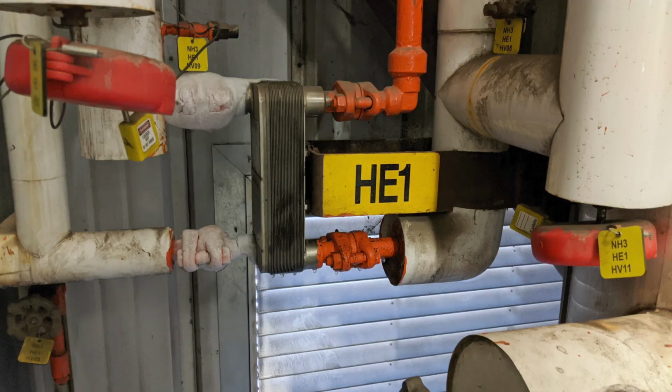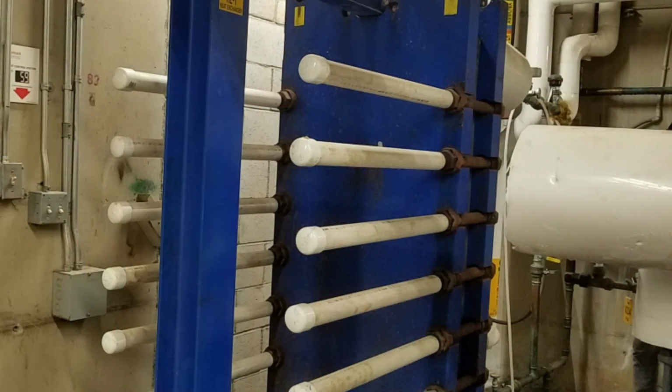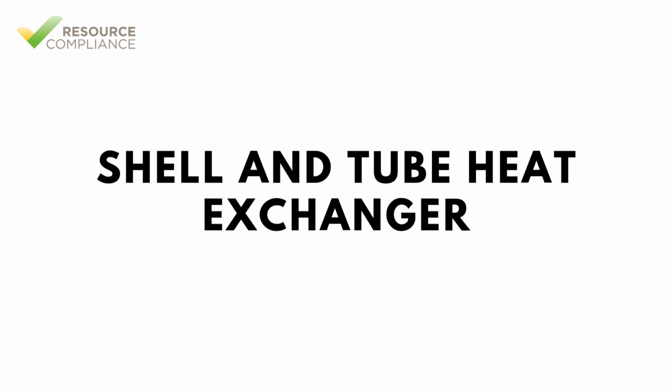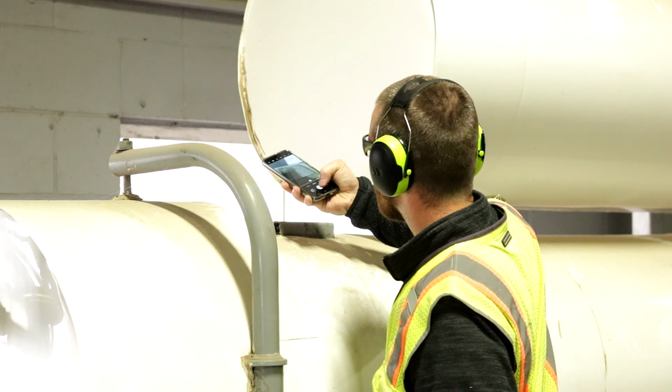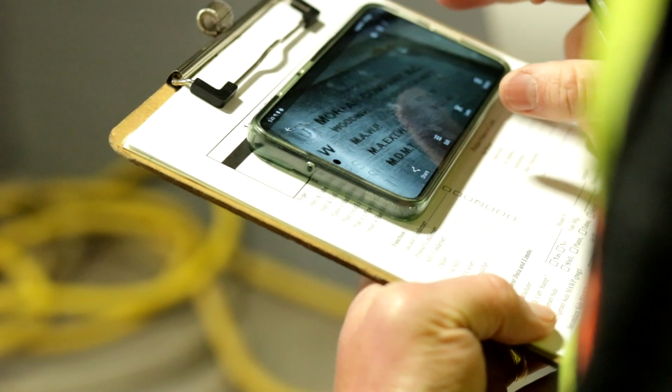Many different types of fluid cooling evaporators are used in refrigeration systems. All fluid coolers, however, use a refrigerant to absorb heat from a fluid. The refrigerant and fluid are segregated so that they cannot mix, but the design is such that heat transfer is maximized. A shell and tube heat exchanger is a common type of fluid cooling evaporator. Shell and tube heat exchangers consist of a bundle of tubes located inside a cylindrical shell. The shell is typically an ASME pressure vessel.